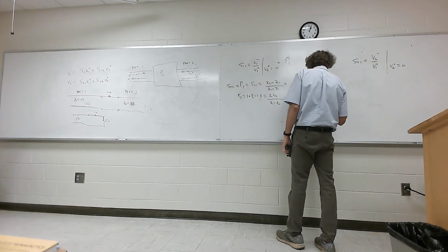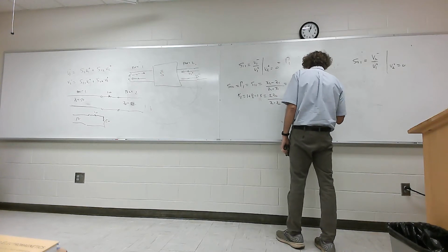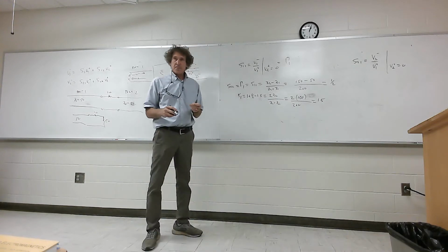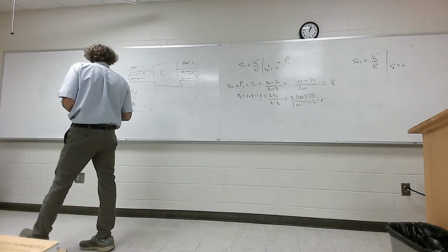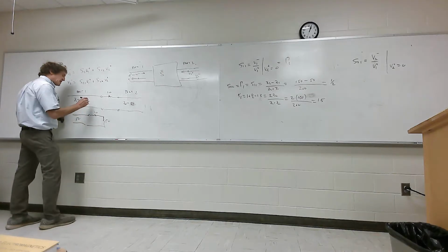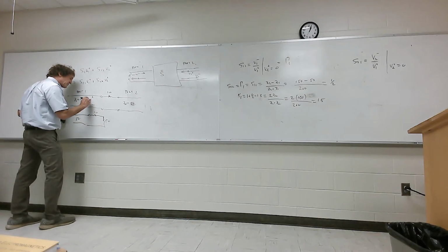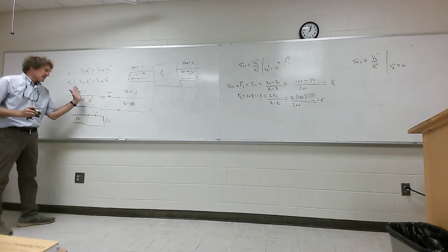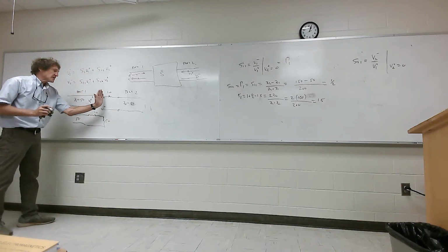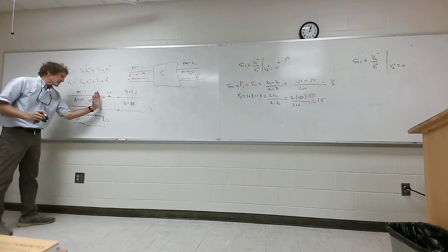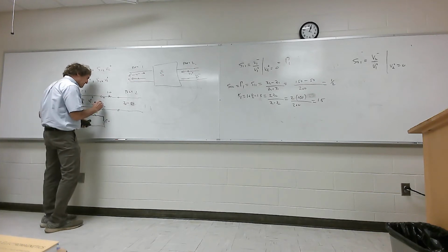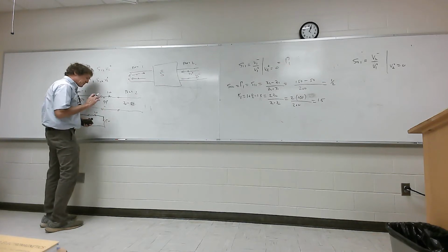So that's 300 over 200, or it's gonna be 1.5 as well. Either one will get it to you, but that's the transmission coefficient. Now what that does is, it tells me that if I have a signal coming in here that's V1 plus, the voltage here, not on this side, not where the transmission line is, just on the other side. Because remember, when the wave comes in and hits, some of it is reflected, right? What's left on the other side is actually gonna be that transmission coefficient times V1 plus.